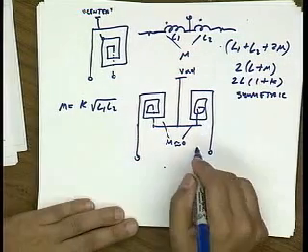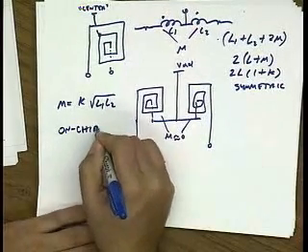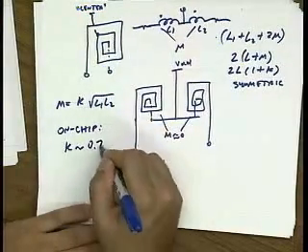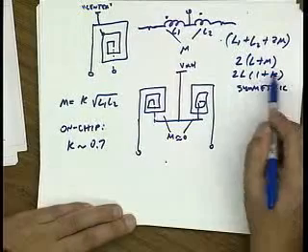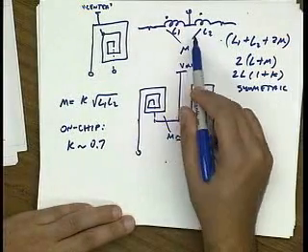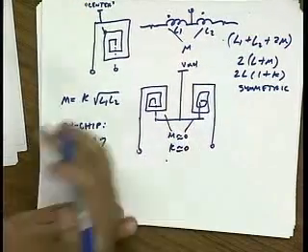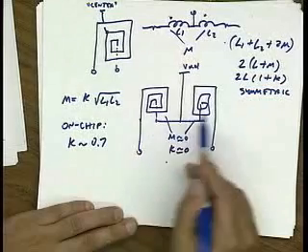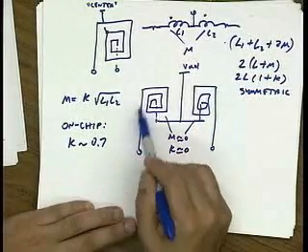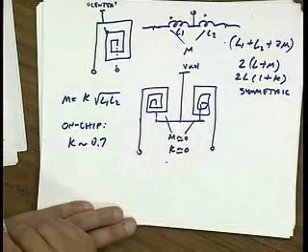Right? So let's say on chip, typical coupling factor is about, for this kind of structure, 0.7. So this inductance is actually pretty nice. There's a 70% boost due to the mutual coupling. If I do it this way, and K is practically 0, maybe it's 1%, there's only a 1% increase in the inductance, so practically nil. So I have to actually make these windings much bigger to get the same value of inductance.